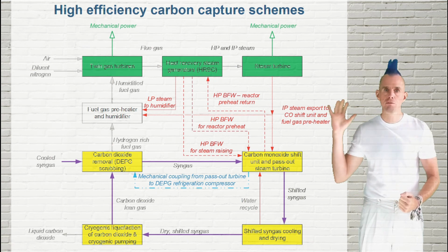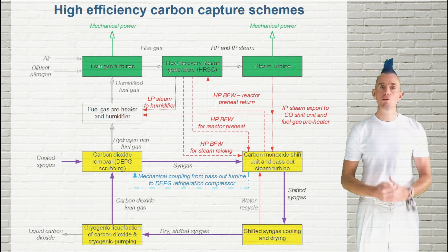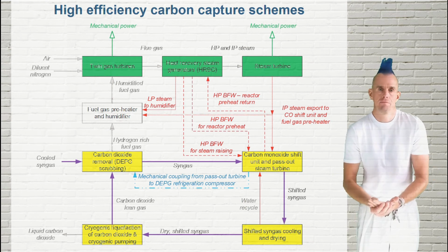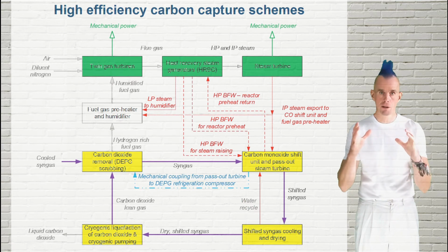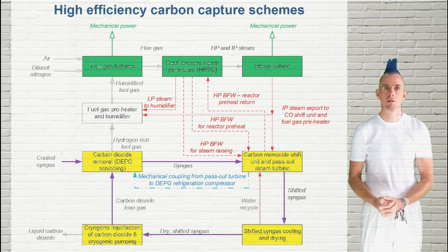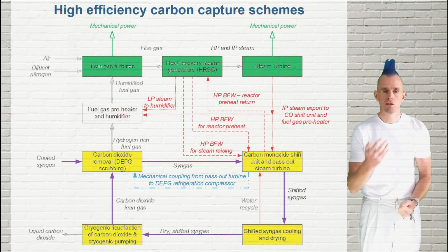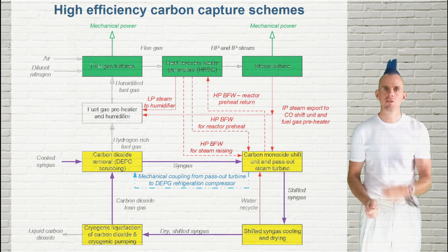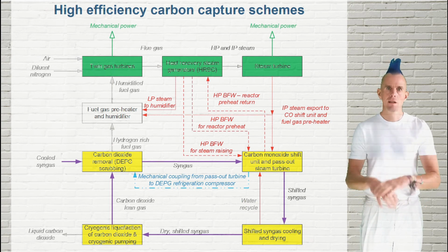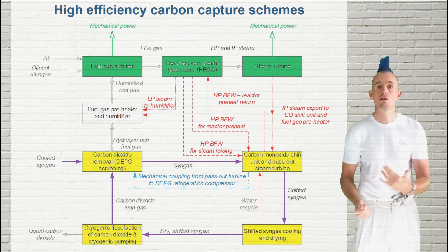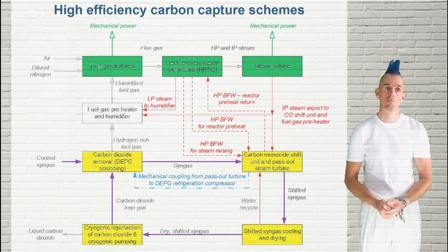One of the neat aspects of this technology is that you don't treat the carbon dioxide in the gas phase. What you do is you refrigerate it and liquefy it, because there is part of the carbon dioxide phase diagram where liquid carbon dioxide exists. It is far safer, far simpler and far more energy efficient to pump liquids than it is to compress gases. Gas compressors are huge, expensive, semi-hazardous pieces of machinery. They're usually one of the most expensive bits of machinery you see on a plant.